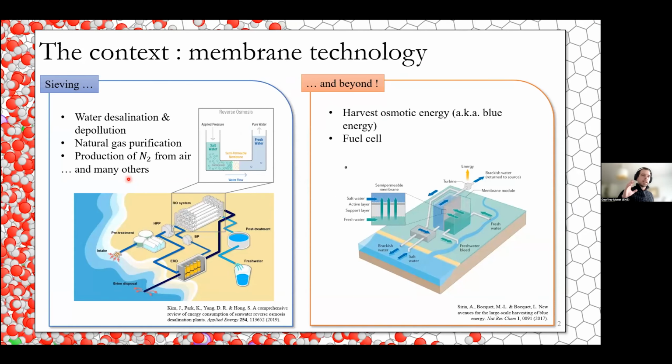Well, membranes, as you may know, are really at the center of many technological devices that may have huge industrial and societal implications. For example, desalination becomes even more important with the increasing water access issue. Today, the major part of desalination is done thanks to reverse osmosis. Reverse osmosis is just sieving seawater under a huge pressure drop across a semi-permeable membrane. This method needs a large area of semi-permeable membrane that must be cheap and mechanically robust.